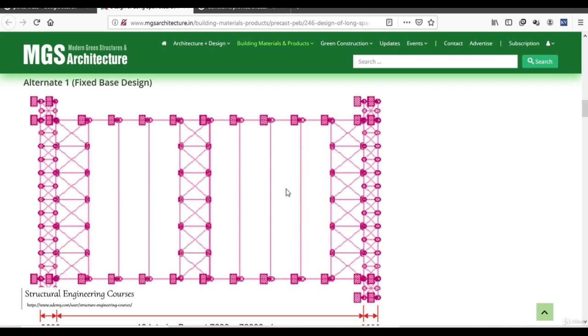You should note that, for example, if the length of the building is in the range of 90 to 100 meters, and that building is in steel, the expansion and contraction in the case of severe temperature change may go up to 60 to 70 mm also. I am talking about the total length of the building. Those expansion and contraction are not balanced just like that. They are either balanced in the form of the bracings, or in the case of the RCC structures, the extra stresses do come on the structures. So that is the reason why expansion joints are provided.